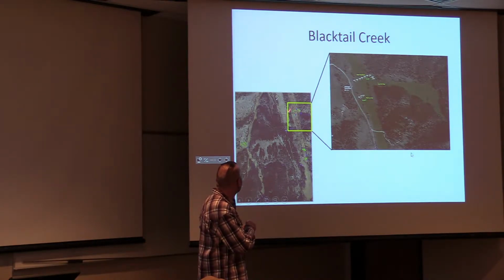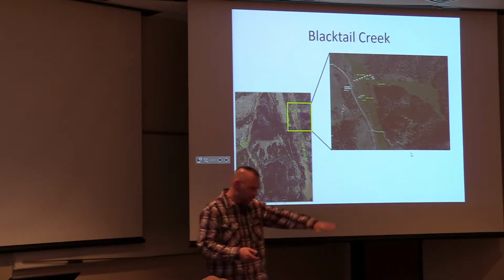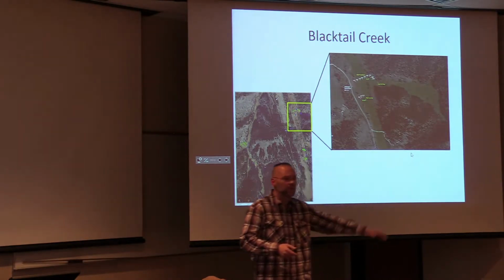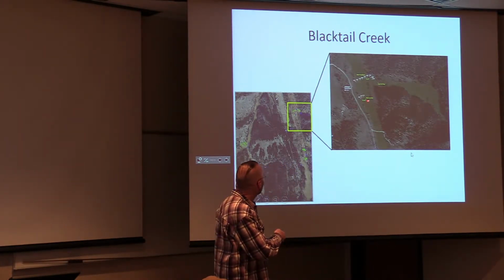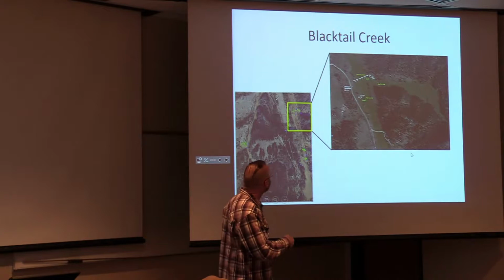This is the main area, and maybe I'll show a little bit of the control, but over in the restored site you can see there's a line of wells going in this direction because we anticipate groundwater flow moving in that general direction, and we pretty much know that groundwater is flowing along the floodplain in that direction. We have some wells coming up onto this little bench, so we come up not too high, maybe 5 or 6 feet, and there's a few wells up on the bench, and a little line over here of wells where you start in the floodplain and move up into the bench.